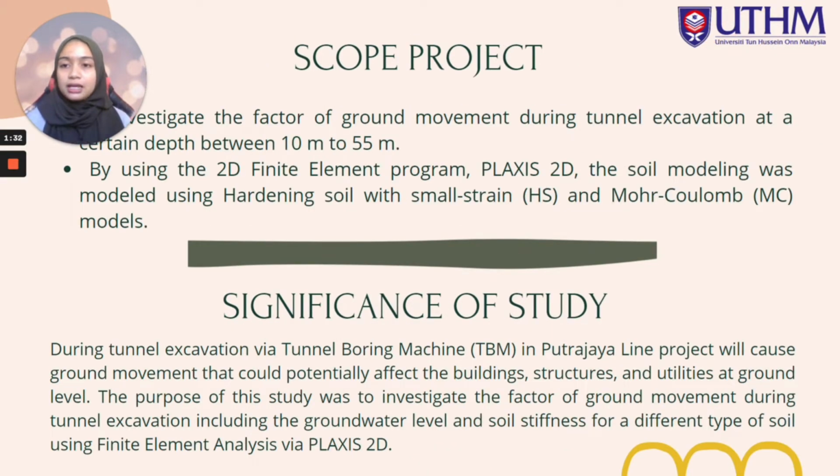For the scope of the project, I will investigate the factors of ground movement during tunnel excavation at a certain depth, which is between 10 to 55 meters. By using PLAXIS 2D, I will build a soil model using the hardening soil with small strain and the Mohr-Coulomb model.